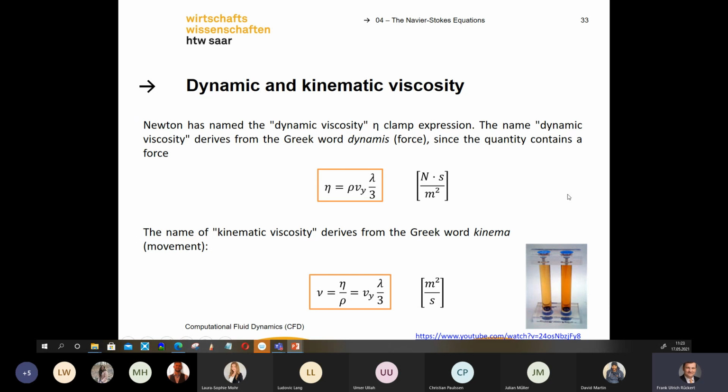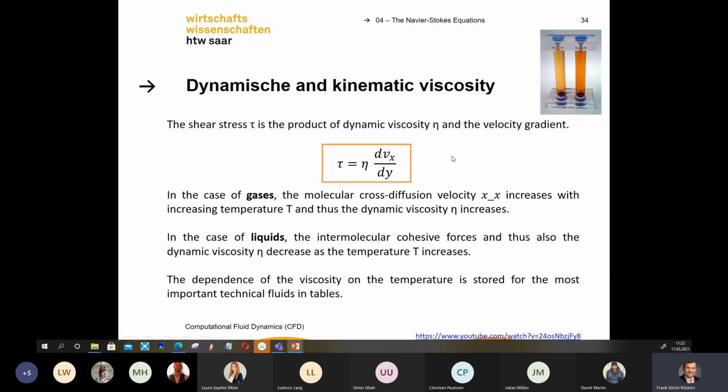Okay, that's something I have to show you in ANSYS, where you can find this field where you enter the viscosity. We have dynamic and kinematic viscosities, and of course they are different for gases or for liquids, and they also depend on temperature. If you have a gas and a higher temperature, the gas gets somehow thicker, so the viscosity rises. For example, in a fire or in a hot temperature, the viscosity of the gas is really higher.